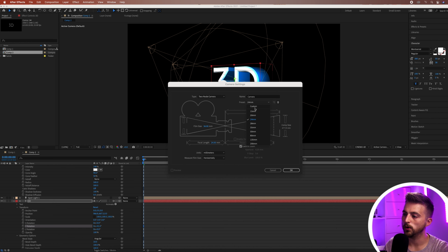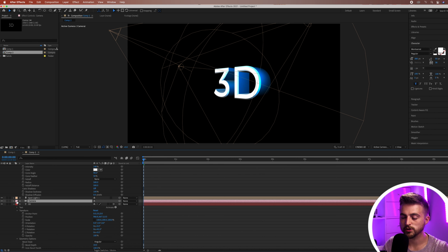Of course, if you are working with actual footage and you're putting 3D text into your footage, then you want to try and match closely the type of shot that you're using. So if you use 24mm lens and that was your focal length in the shot, then try and select a 24mm camera here. But if you're just creating some 3D text for an intro or a graphic or something, then feel free to select any one of these. The general preset is 50, but I'm just going to select 24. We'll press OK on that, and then we'll just go into that camera.